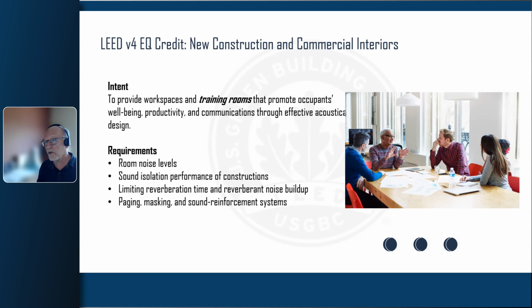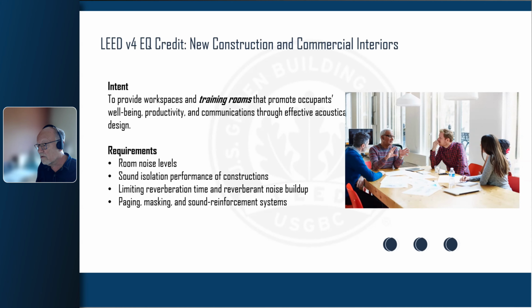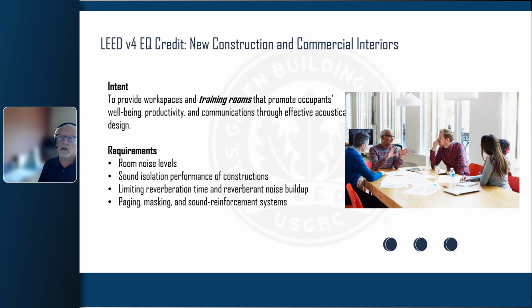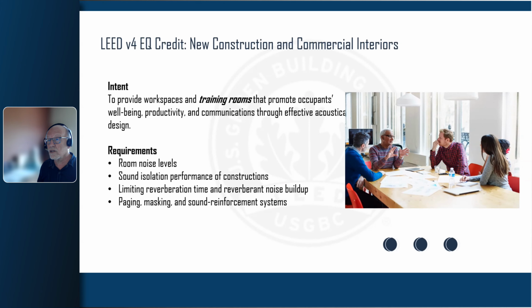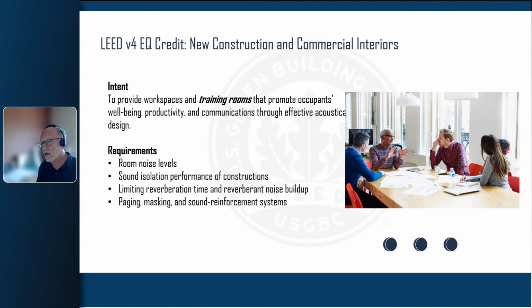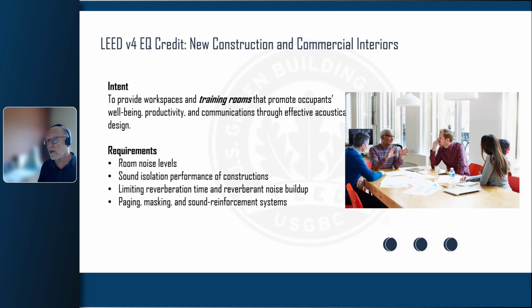It'll improve the performance. You might improve from an STC 30 to an STC 33. But if the door panel hasn't been tested as part of an assembly, you're not going to get a high level result. And that may be fine. You may be in an area that doesn't require high performance acoustic attenuation, or there may not be a budget for it. But without a perimeter and bottom seal, you won't get above STC 30.